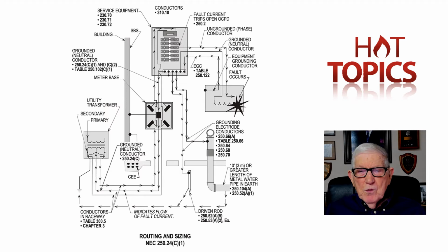You see where these systems are here, that'd be 5 ohms, 5 ohms here, 10 ohms into 277, 480 volt. You divide the 10 ohms into 277, it's about 28 amps that would work its way through this earth back to here. That's why this grounded conductor has to be large enough, see, to carry your fault current.